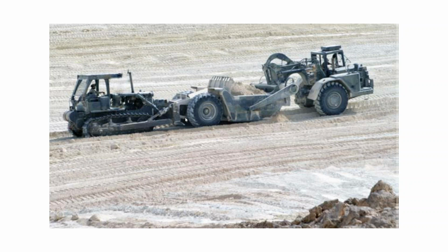Here is the rear end for the pushing, and here is a cat that is acting as a push cat with a push blade that has the shock absorber so as not to damage either vehicle. It's a pretty straightforward operation. The push cat pushes on the scraper. This tractor will pull the scraper across the road, but it needs this extra horsepower when it's being loaded.